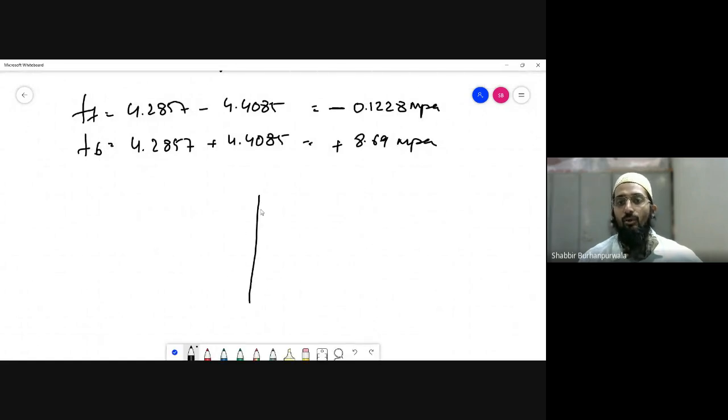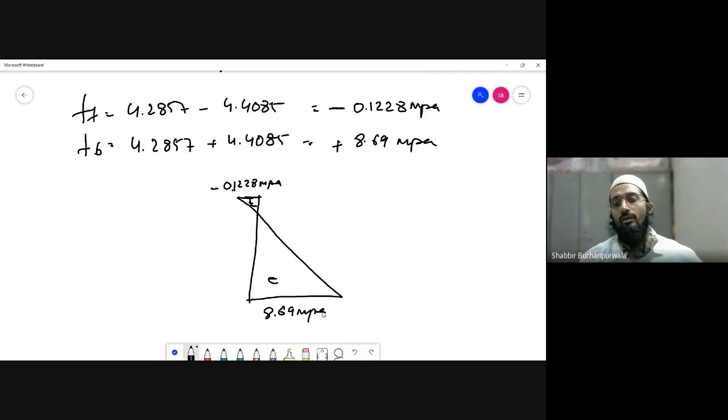So please always make the stress diagram. Suppose we are showing this direction is negative, this direction is positive, so show it in that way. Or you can say this is compression and this is tension, like that. The diagrams can be exaggerated also, but try to make it proportional. At the top fiber, MPa at the bottom fiber. So top fiber and bottom fiber.